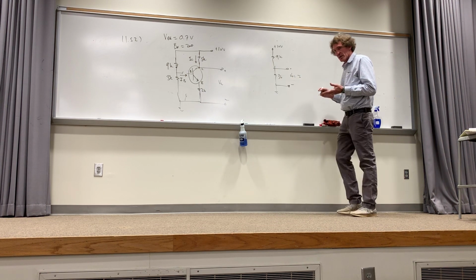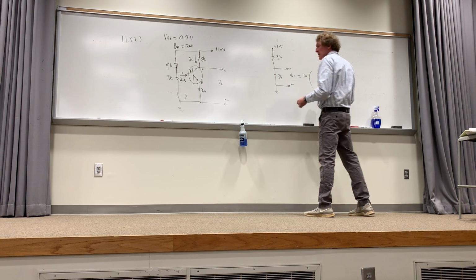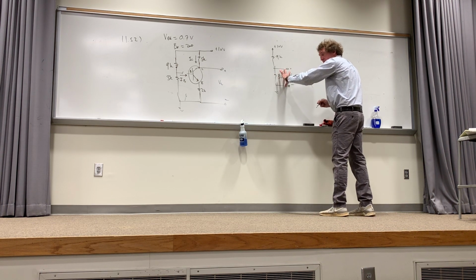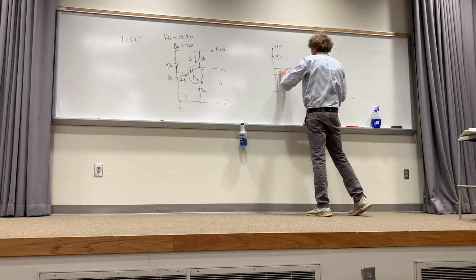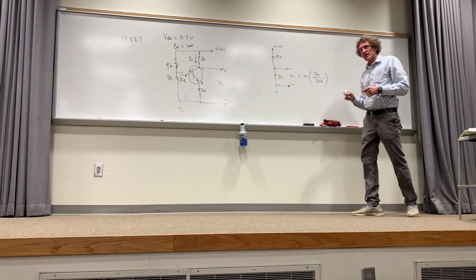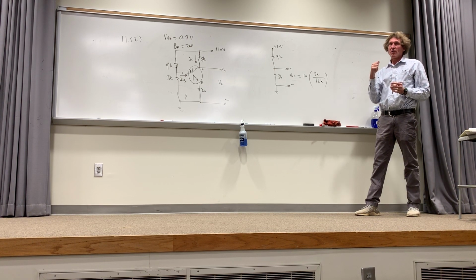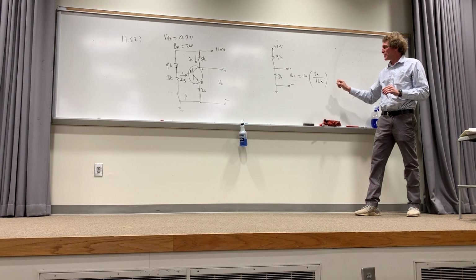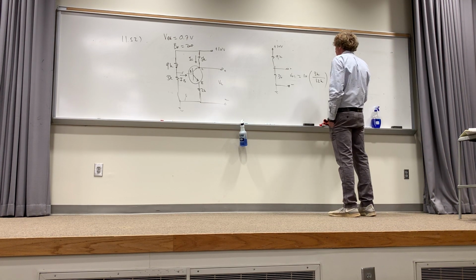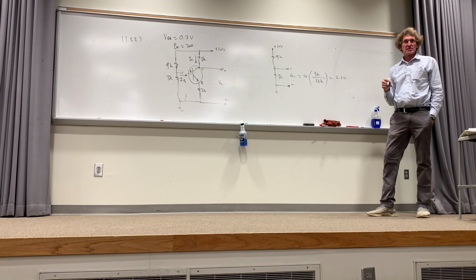Well, how much voltage is here? Just look at it. I got 10 up there, right? So it's 10 times the resistance we want the voltage across over the sum of the two, right? You all agree with that, class? That's simple voltage division, isn't it? We've done that all semester, basically. Well, what's that going to be? That's 1/4 times 10, or 2.5 volts, isn't it, class? That's the open circuit voltage there. Y'all with me?